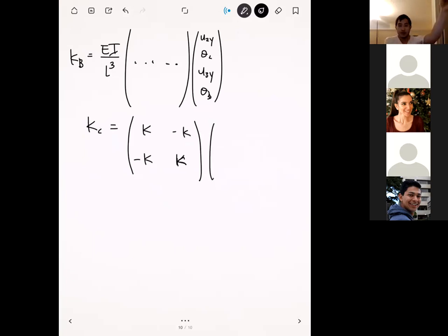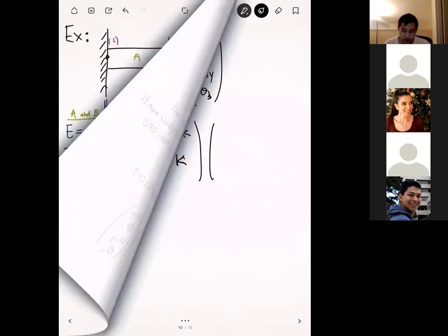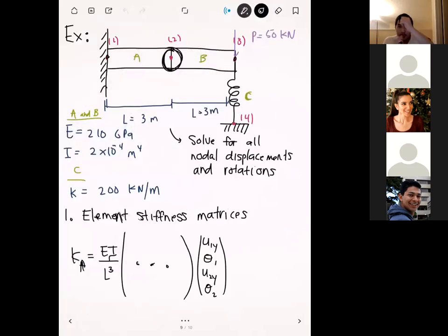Now we come to the part where we have to list out its degrees of freedom. Remember, the spring can only compress and stretch, so the spring can't handle any transverse displacements. In other words, the spring can only displace this way and this way. Just by the nature of the force, we know that it's going to compress. We have to turn our heads a little bit because our spring here is vertical.